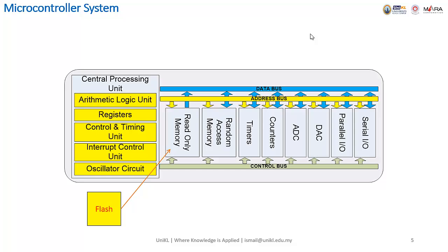We can erase the flash by block, or erase all the data inside together, and then we can write by block. We cannot write the data by byte. Compared to the EEPROM, where we can write data by byte, flash must be written at least in blocks.